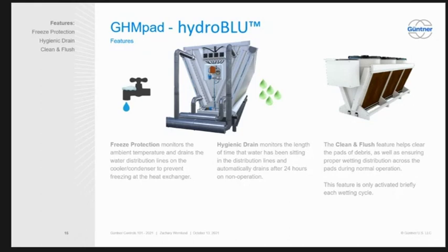A lot of times what I see is it's a visual thing, because it's a once through system. It's not a system where we recirculate water, because whenever you recirculate water, that's a whole other issue. You've got water treatment and pumps and other things that you have to do to recirculate water. And it also opens up the door to nasty things like Legionella. So we don't recirculate water on these units, but we do meter it and make sure that you're not using an excessive amount of water.